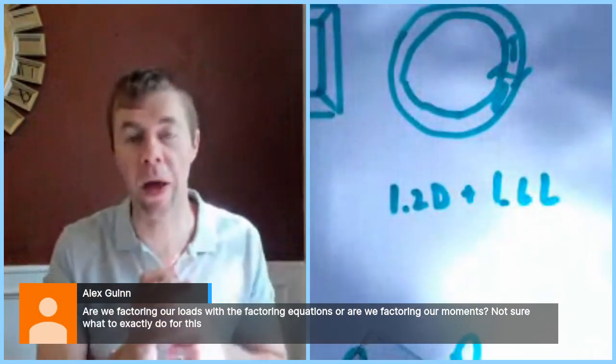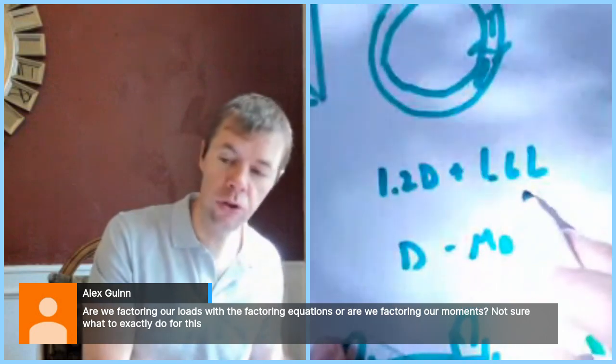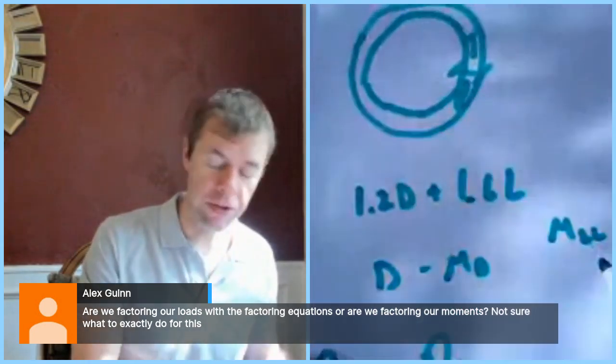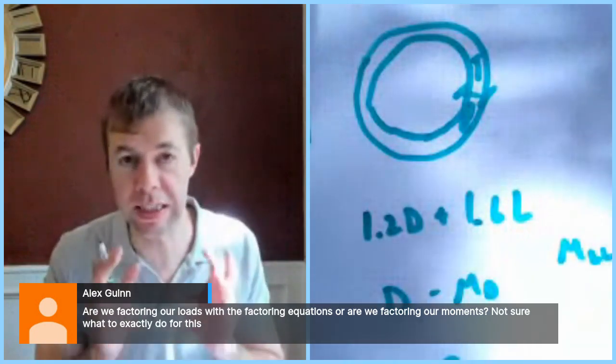You can do either one, Alex. You could put your dead loads on your structure and find your moments from those dead loads. You could put your live loads on the structure and find your moments from those live loads. And you could factor the moments just like you factor the loads. It doesn't matter. It literally doesn't matter.